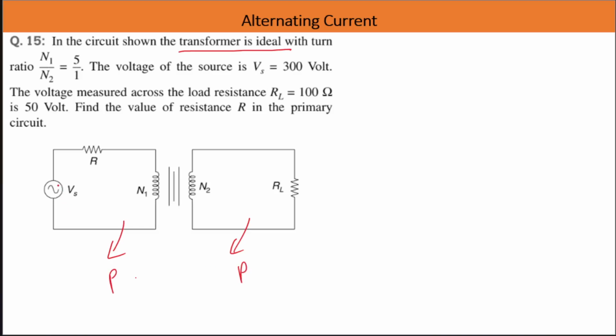In the primary circuit there will be a voltage source, and because of it there will be current in this circuit, and because of this current flux will get generated across this inductor, the primary inductor. This is called the primary coil, and since current is changing, flux across it is changing. Now flux is passing through this and that will get linked with the secondary coil over here,